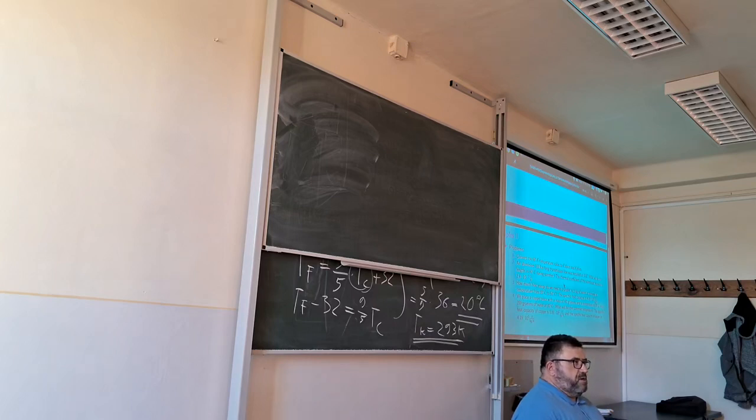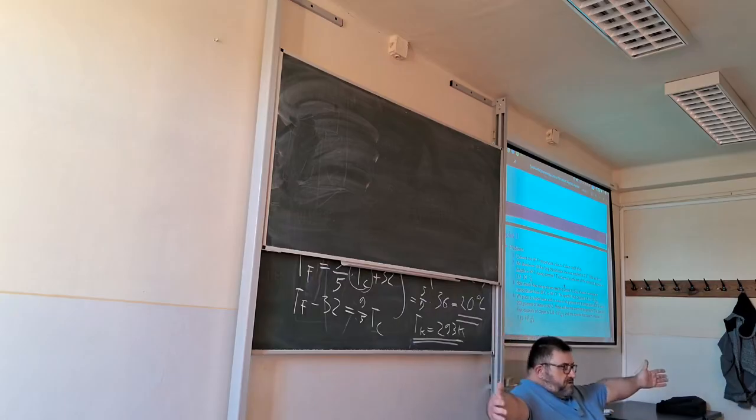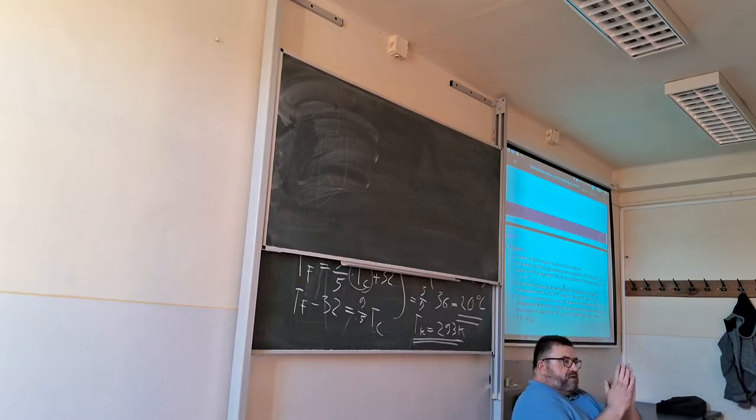No. 0.01 millimeter for 1 meter. However, if you have 100 meters, then that's 1 millimeter. If you have 200 meters, then that's 2 millimeters. And 2 millimeters displacement in concrete can count.